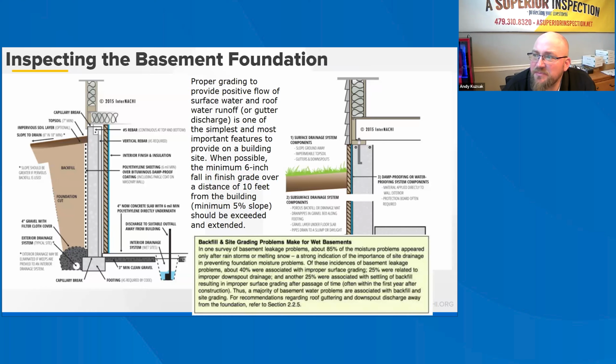Moisture protection of foundations by the owner or builder should err on the conservative side when there is reasonable doubt about the moisture conditions on site. The moisture resistant practices presented in this course serve as a resource for inspectors and can be considered during the construction of a building. They are cost effective compared to correcting moisture problems post-construction and reduce the risk of moisture issues in other parts of the building by protecting the foundation, which is a prominent point for moisture. This is particularly important if backfill practices are not reasonably controlled to prevent settlement.